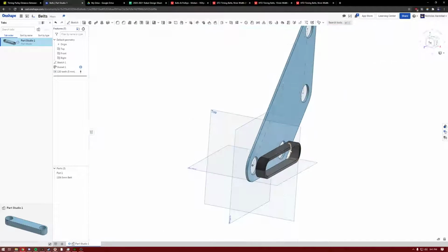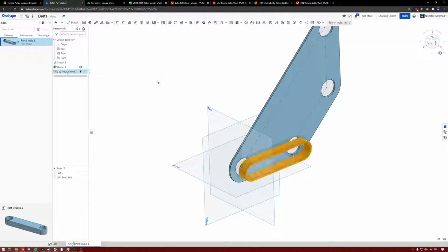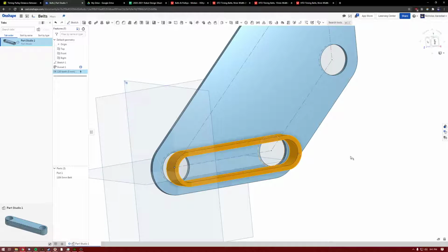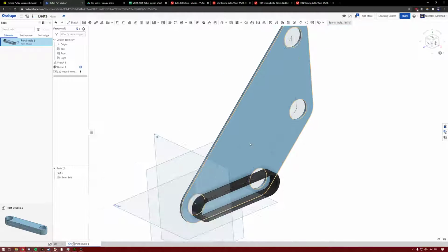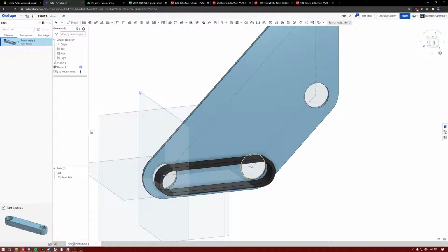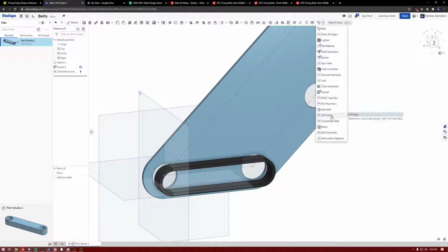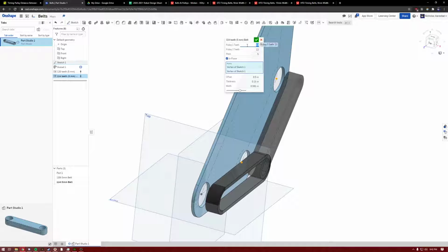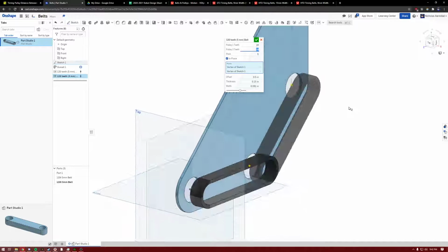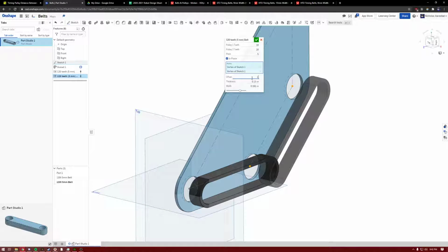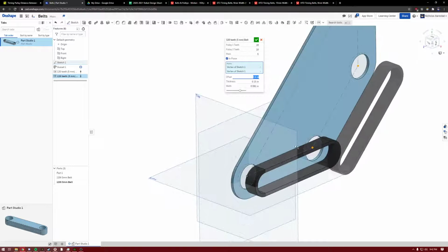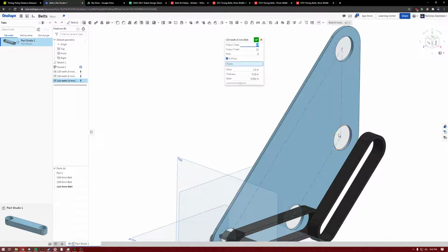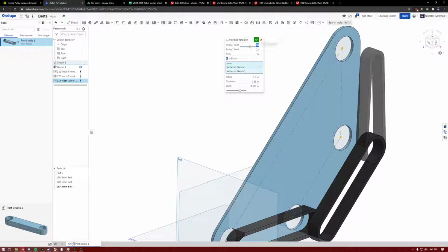Now I'll show you how I would derive these. Oh, and then the other thing here. Even in cases where I have duplicates, this is one of my big rules, if anybody had listened to me: I hate duplicate parts. You have to be really careful when you have duplicate parts. In a case like this, I'm often fine with it, because I find myself oftentimes changing belt dimensions later. So it just saves me effort to say these are all going to be separate belts and then add them up later, over making these one and then doing all the constraints here. This also saves time if we inserted these into a part studio. So I'll show you what I mean by that.